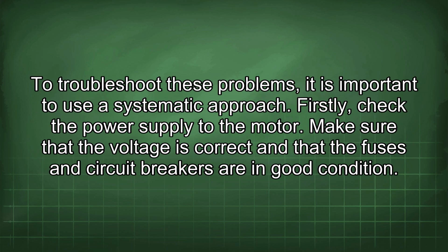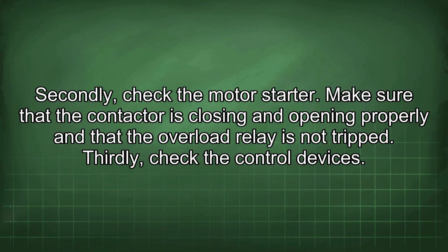To troubleshoot these problems, it is important to use a systematic approach. Firstly, check the power supply to the motor. Make sure that the voltage is correct and that the fuses and circuit breakers are in good condition. Secondly, check the motor starter. Make sure that the contactor is closing and opening properly and that the overload relay is not tripped.